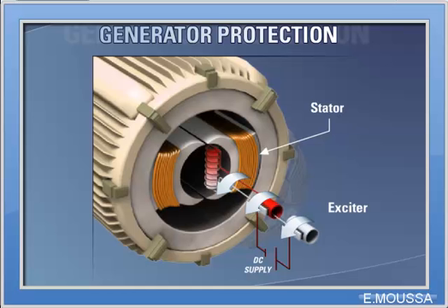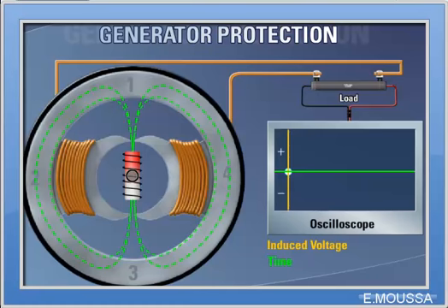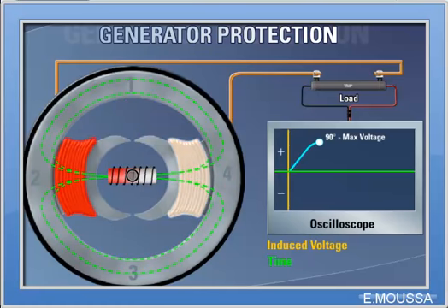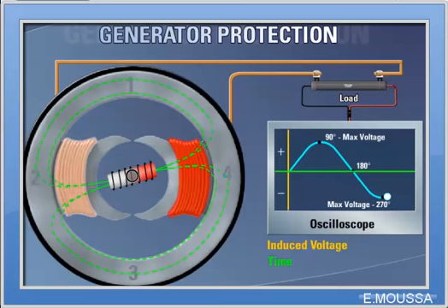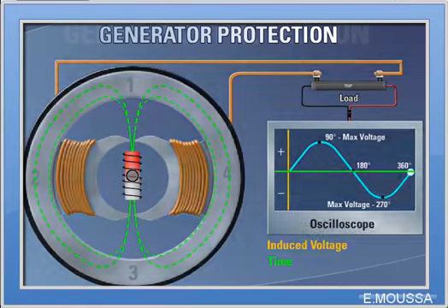The stator is constructed from two electromagnets, or poles, wired in series to a load, and as the name implies, remain stationary. As the exciter rotates, its magnetic field cuts through the windings of the stator poles, inducing a voltage, and hence current, which will flow through the attached load as shown.